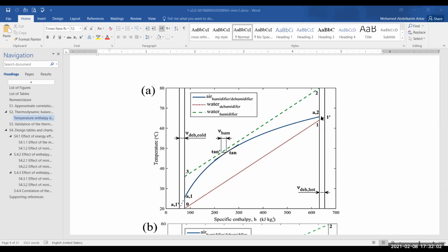the dehumidifier. Whereas the air enters at high temperature, it will condense, it will cool down because of the interaction with the cold water inside the tubes. Air is going to cool down, but it will maintain its saturation condition until it leaves here. The condition is best if the air is further cooled down to the inlet water temperature. And that is another, smaller enthalpy pinch at the inlet condition. What we do, we compare this enthalpy pinch and this enthalpy pinch, and the smaller one of them is what we consider in estimating the effectiveness of the unit.